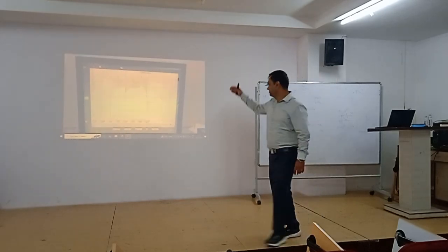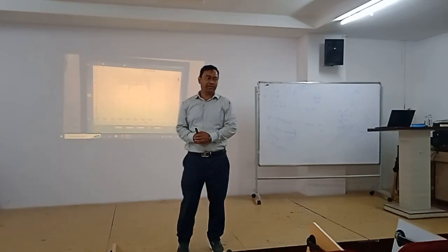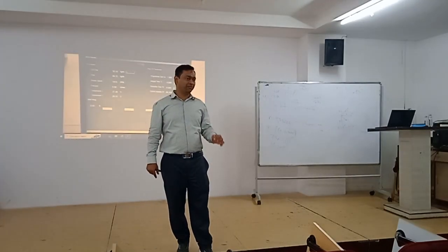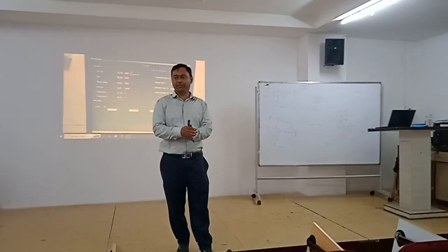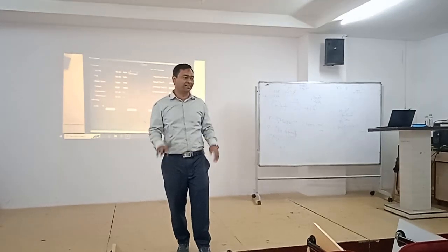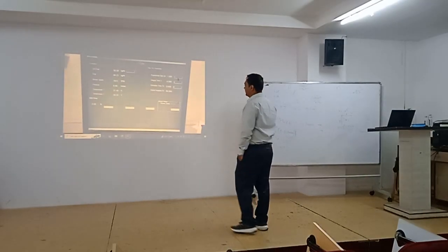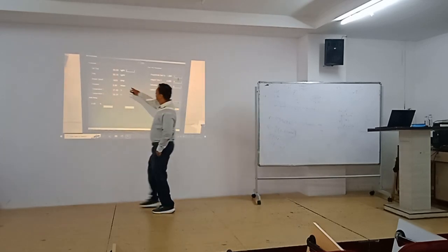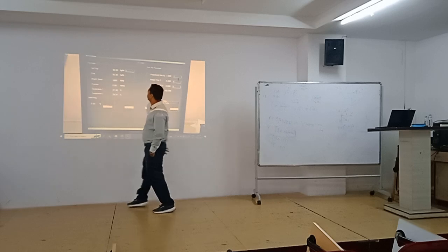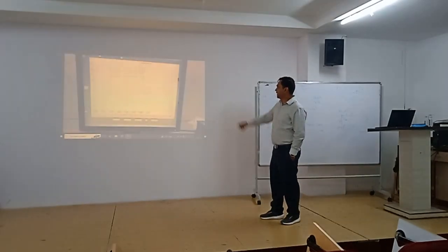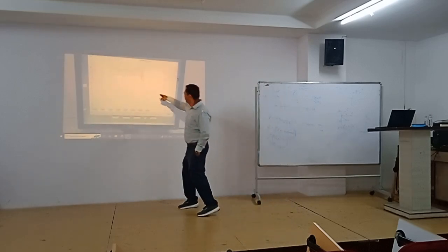And actually, the exact definition, if we go for settling time in a control system, it's actually a 2 to 5% band. So 2% band means once something comes within 98% to 102%, it's considered to be settled. The variation is not considered at all. You see, it's almost as you see. So now we made it 0. So it's coming to 0.